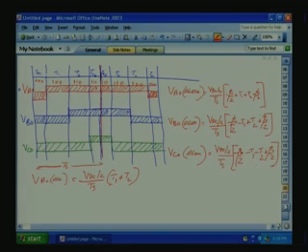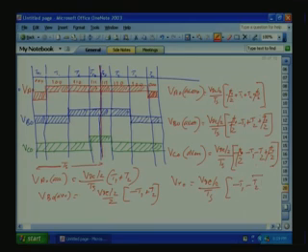Okay. And what is VB0 average? VDC by 2 into minus T1 plus T2. And VC0 is equal to minus of VS0. So, that is equal to VDC by 2 divided by TS into minus T1 minus T2. In a sector, with T1, T2 periods, VC0 average is equal to minus of VS0 average.